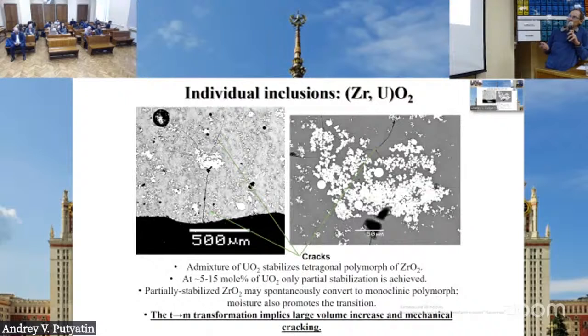We have very interesting conclusions on oxidized cladding. Oxidized cladding is, of course, zirconium dioxide with a mixture of uranium. But what is important is zirconium dioxide, which is known as baddeleyite. Baddeleyite is quite a common zirconium-bearing mineral, but when you make zirconium dioxide at high temperatures, it goes to a different phase, whereas baddeleyite, or so-called monoclinic zirconium dioxide, is a low-temperature modification.